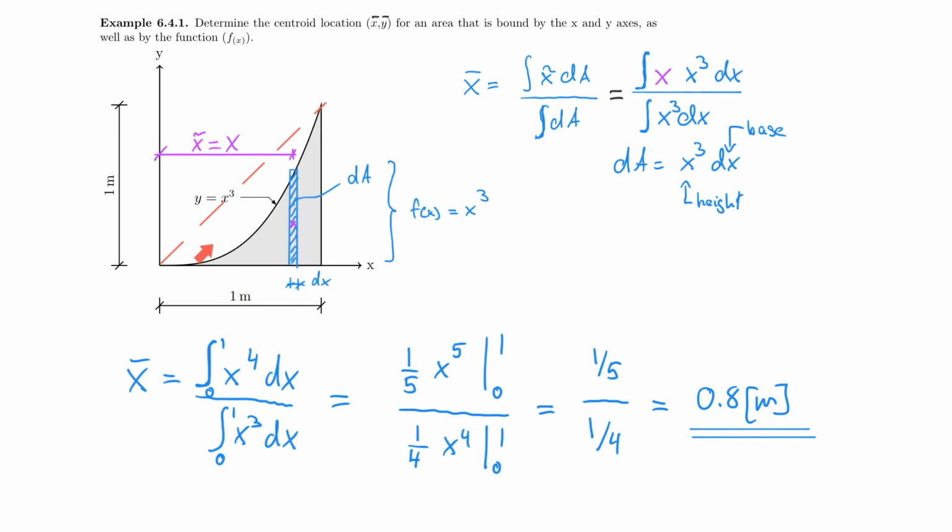And now, in this case, I'm actually carving out a component. That means the material gets heavier on the right side relative to where it was when it was a triangle. And therefore, it needs to be larger than 0.66, which is the case. Also, it cannot be larger than 1, and that is also the case. So I solved this. So that's fairly straightforward. So I solved for x bar.